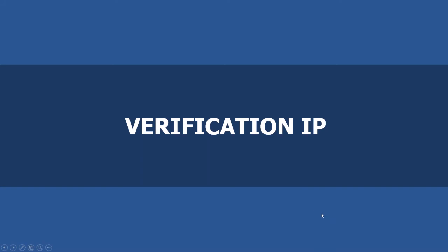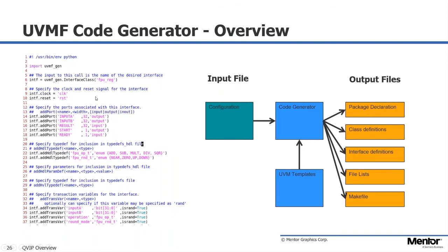So the UVM framework helps you with a template-based manner to create that code. For every one of my agents, instead of needing to write those 15 different files for that agent, what I end up doing is creating a template. And that template says, okay, here's the IO for that thing. So for this FPU, I've got input A and input B. I've got a result coming back.